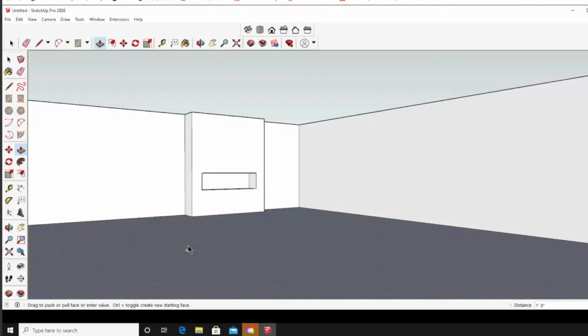On the bottom of page 6, we're going to start creating a mantle. The mantle is going to be 8 inches above the fireplace opening, and it's going to be 96 inches, the full width wide. So I'll use my guideline tool again. I clicked, released, pulled up, and then I'm going to hit 8 on my keyboard and enter. I might as well go to this side as well. So now I have a nice line that goes all the way across.